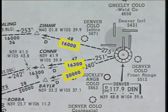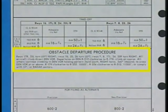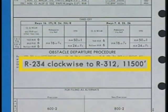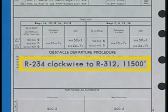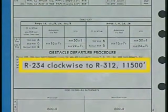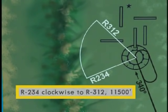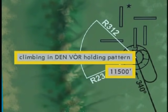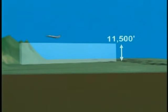Notice the high initial minimum en route altitudes in this graphic departure procedure. Now let's look at the associated textual departure procedure. Note the altitude requirement for aircraft departing westbound from Denver between the 234 and 312 degree radials to ensure obstacle clearance. If you're flying this textual DP for your initial departure, you must climb in the Denver VOR holding pattern until at or above 11,500 feet before proceeding westbound.